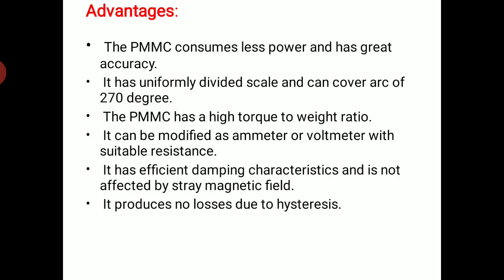So, the advantages. PMMC consumes less power and has great accuracy. It has an evenly divided scale, and PMMC has a high torque-to-weight ratio. It can be modified as an ammeter as well as a voltmeter with suitable resistance. The damping characteristic is not affected, as the magnetic field is stable. It produces no losses due to hysteresis.